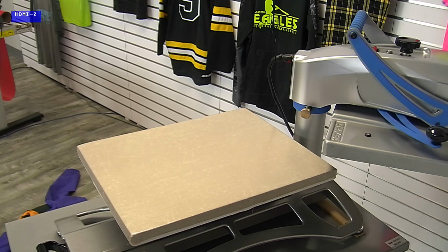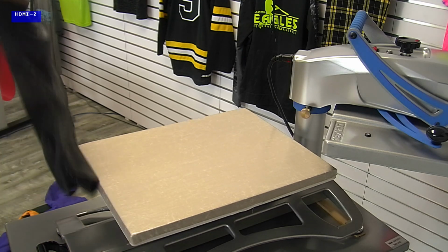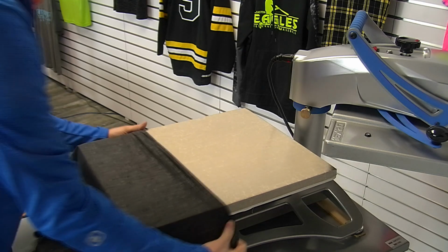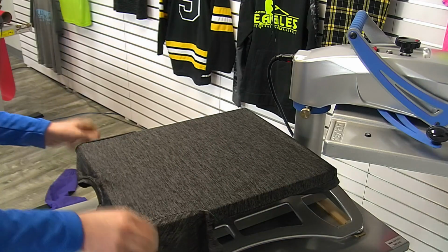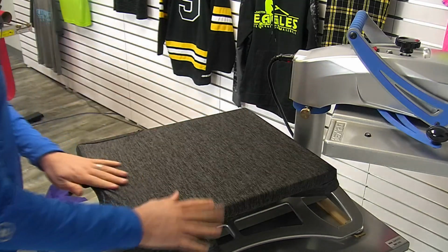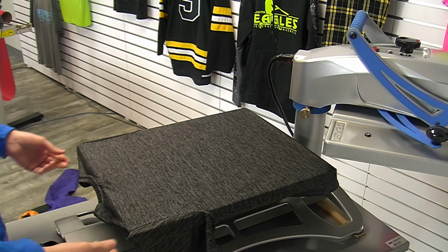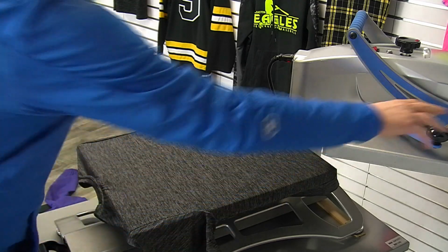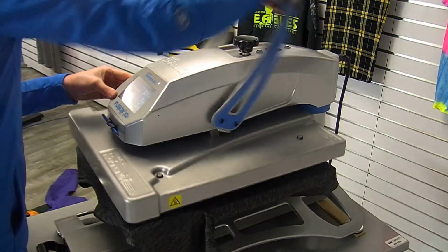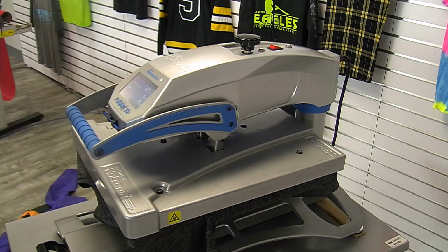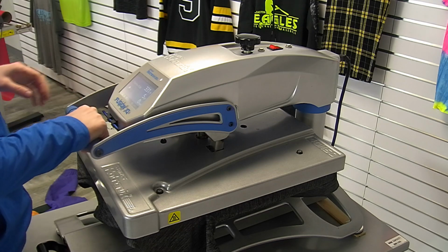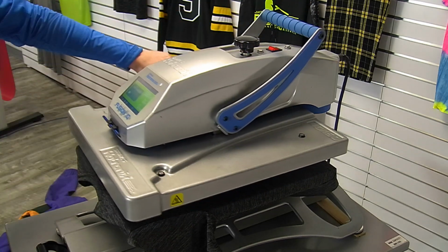I'm operating on the Hotronix Fusion 1620. I'm just going to heat press this onto a performance tee. I'm going to load that on, get to the back of the press. I love that you can split and load these on. Like any material, we always recommend a preheat. I know some of you skip that step. We still recommend it. Helps just to get the moisture out of the garment and get it ready to heat apply.